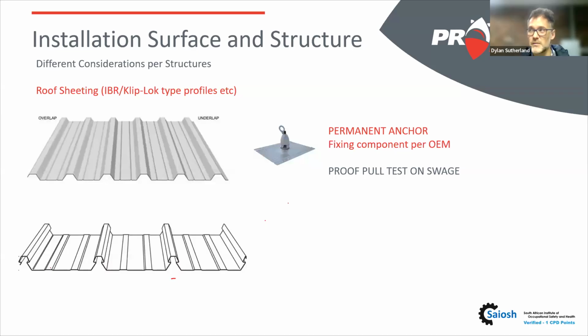Rather, if you're going to put in a lifeline, just put the cable. You give that person that's getting on the roof the ability to connect the moment they get on, stay connected their whole job, get back to the cat ladder, and then disconnect. Keep them safe by making sure they don't have to disconnect.